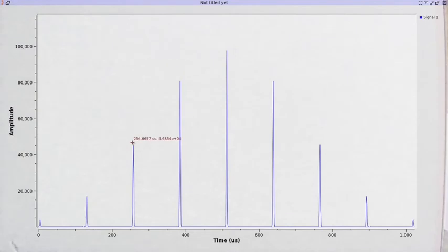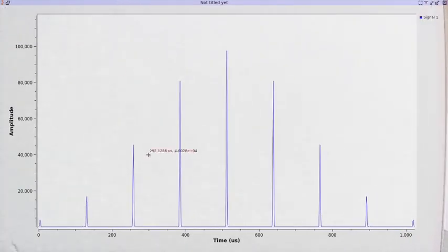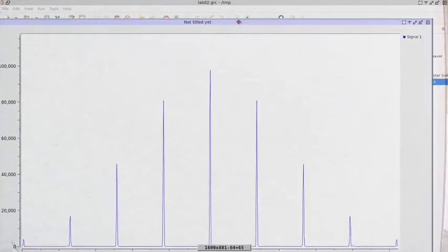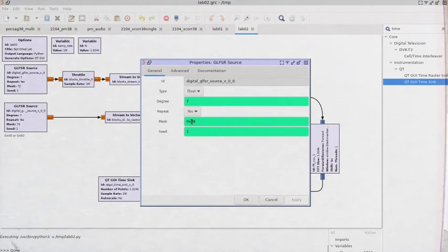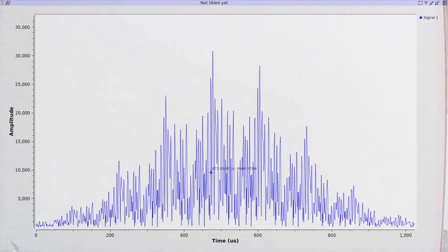Then we have 256 here, so this is the length of the pseudorandom sequence of a degree here. So if we have the same pattern, we see that they repeat. This is actually the shape of the windowing function in the Fourier transform that we have here. We have this Blackman-Harris windowing function, and that's the correlation weighting function here. These are these correlation peaks here. So again, if we take different patterns, we see that they will not repeat, and there will be no coherence peak between these two functions here.